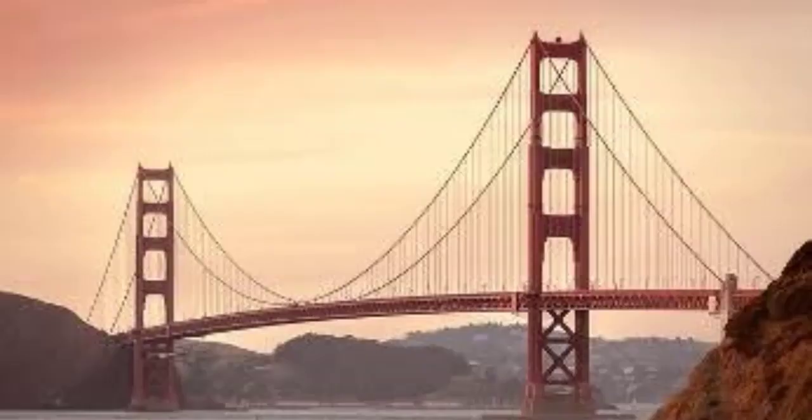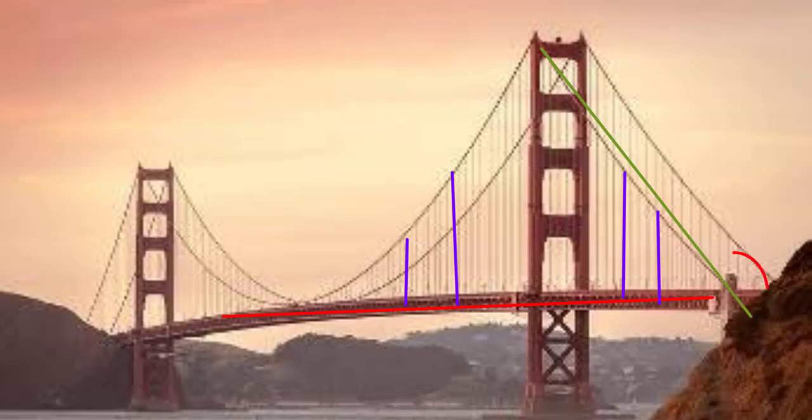Whereas in a suspension bridge, the combined weight of the deck and the vehicles traversing the deck are sustained by the suspenders and then transferred into the main cables. Then from the main cables, one part will be transferred to the anchor, another will be transferred to the tower. From the tower, it will be transferred to the foundation and then into the soil, and from the anchorage it will also be transferred down to the soil.